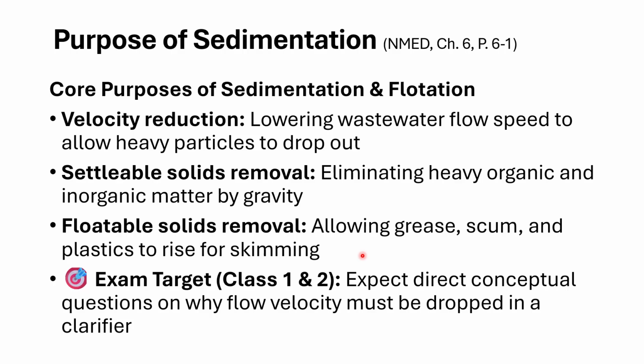So we've got 2 separation mechanisms going on here. We've got sedimentation allowing those heavier particles to settle out, and those particles have a specific gravity greater than 1, greater than water. They're heavier than water, which lets them settle out. The lighter stuff, specific gravity less than 1, floats to the top. So those are the 2 mechanisms, sedimentation and flotation.